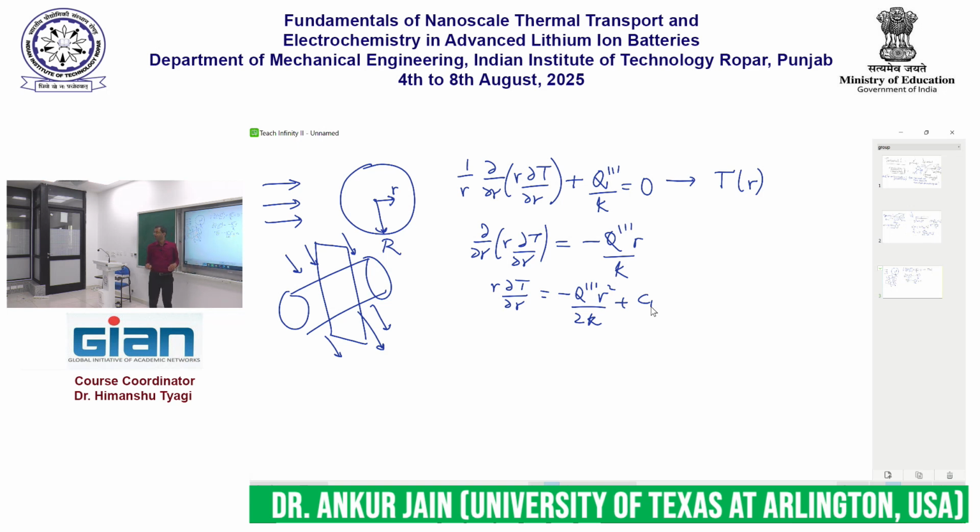And if I integrate it once more, I can take the r to the other side and integrate once more to get T equals negative q triple prime r squared by 4k plus c1 log r plus c2. Everyone with me?